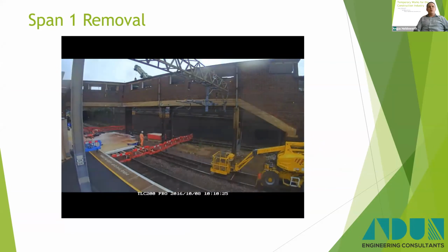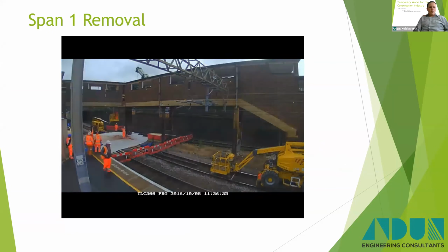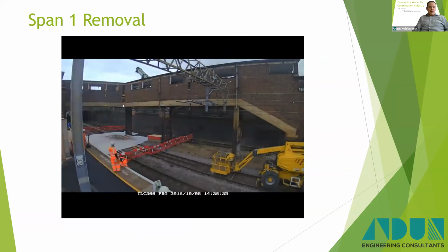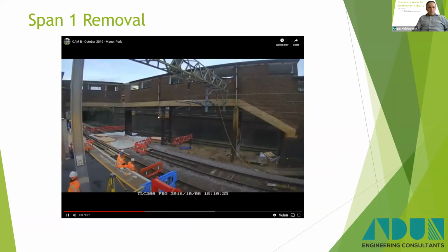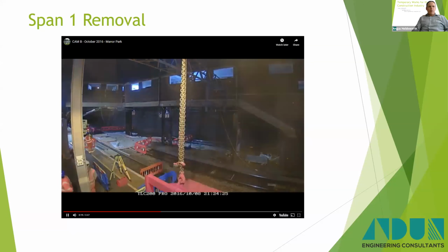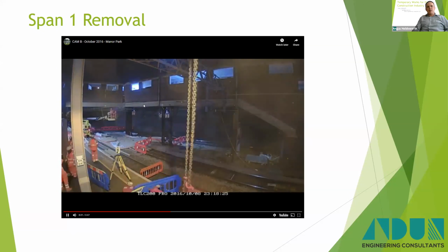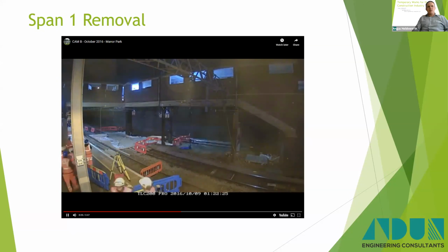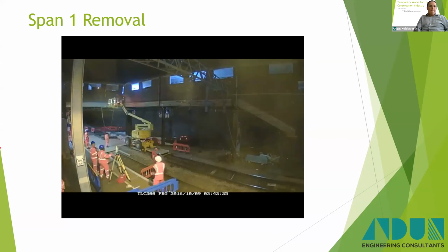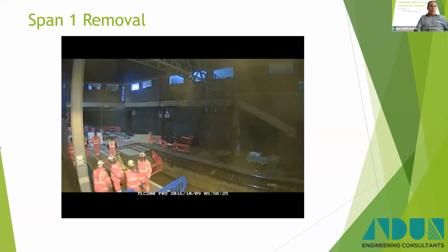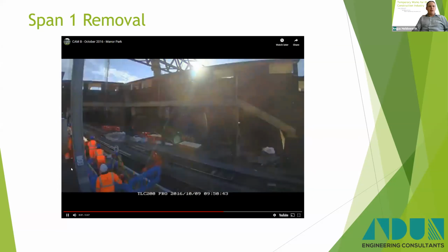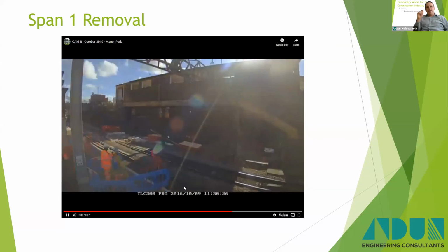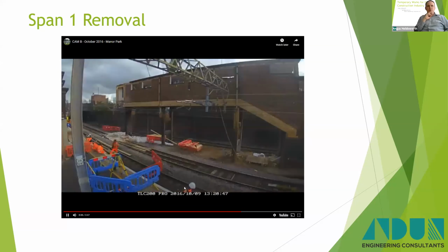So this is a little time lapse of it being done. So you can see it's been cut through up there, released fully. Temporary props gone in over there, was about to go in over there to the wall just in case we knock this as we're lifting this span out. First lifting frame in, second lifting frame in, carefully hidden behind this pole. And there you go, first span up and away, and it's time to tidy up.